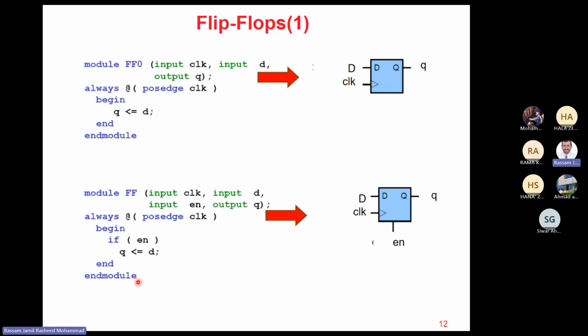Here are flops as we have taken them in the previous section. There is nothing I add here, but just more examples. Here is a classic flip-flop without any reset, and a classic flip-flop with an enable. The thing to highlight here: watch how the sequential circuit is implemented, always with non-blocking assignment, at the positive edge of the clock for the flip-flop. So this is something to watch.